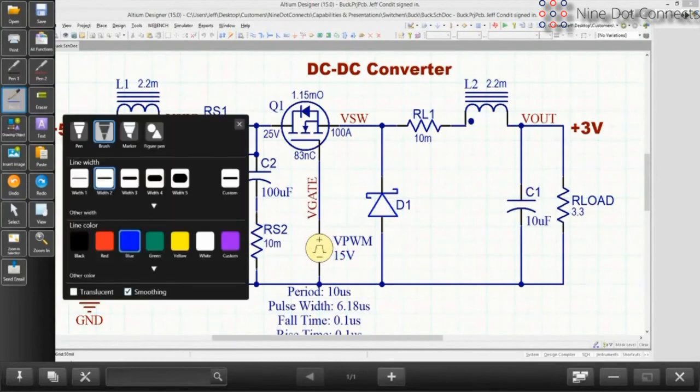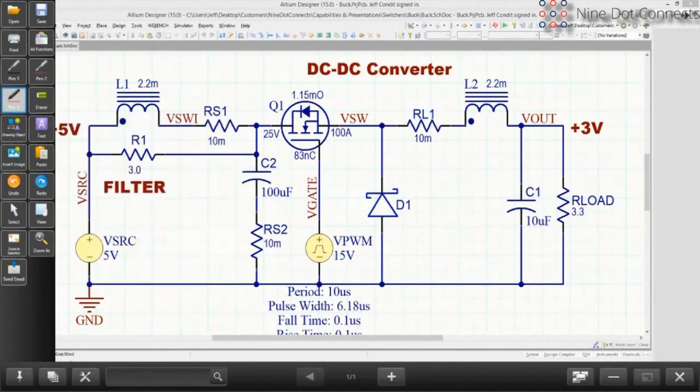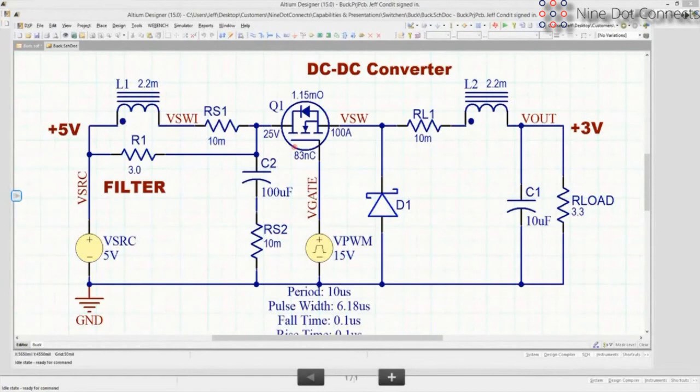So let's go ahead and highlight that. Where is the switching node? Where is the voltage going up and down a lot? Well, it's where this switch occurs. The FET is one switch, and the diode is the other switch. You could use a FET for this diode, but this junction between the two switches and anything else that is attached to it, that is the switching node.